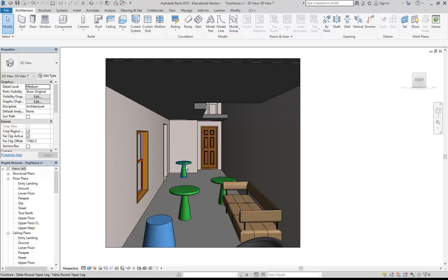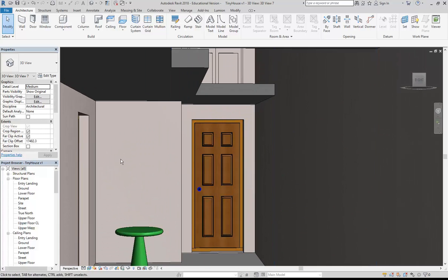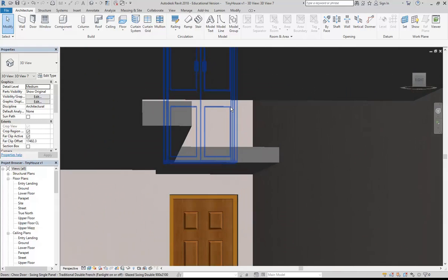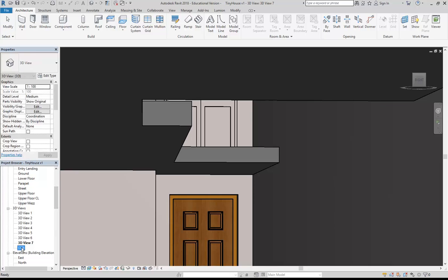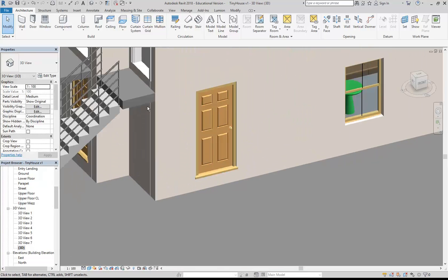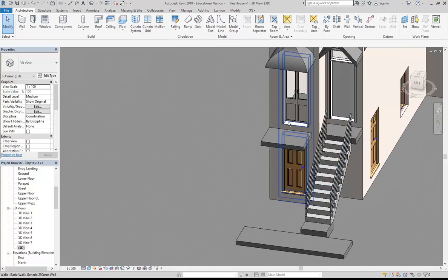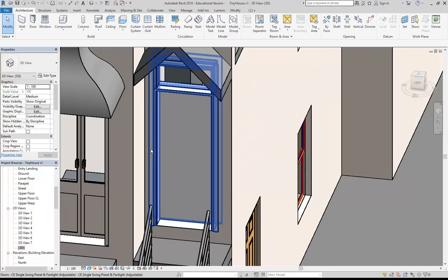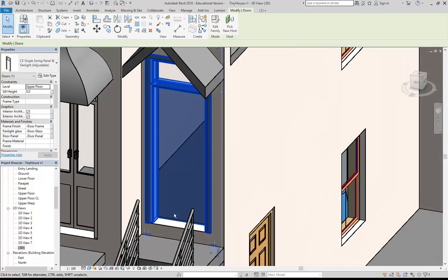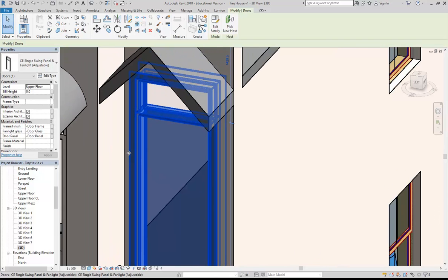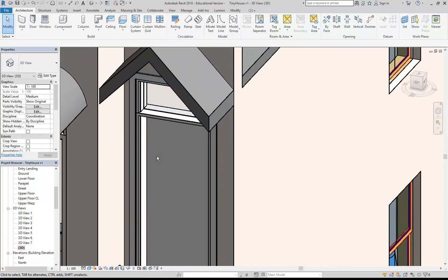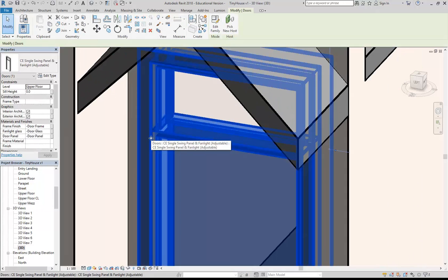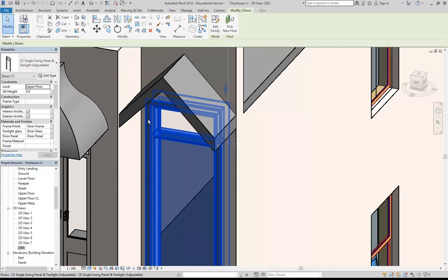And actually maybe that's something I will just show you very quickly, because we've got some here that we can look at, or sorry, on the outside it's probably easier to see. Okay, so this one here, you can see that door on the outside has an architrave. And that's not really appropriate for the exterior side, and even on the interior side you might not want it.